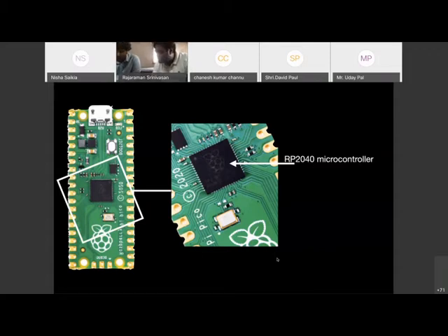The 0 is for the type of core processors, so it's named after that. The 4 stands for this: if you take log base 2 of the RAM divided by 16K and floor the value, you get 4. We have 264 KB of RAM, and dividing by 16K, taking log base 2 and flooring gives you 4.